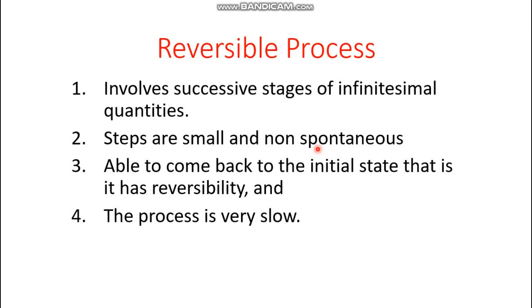and if the steps are small, then it should have the capability to come back or revert back. So the reversible process has the ability to come back to the initial state, that is, it has the reversibility, and from this name it is named the reversible process. So if the path you are choosing has small steps, has the non-spontaneity, and if it has the tendency to come back to the initial state, then that is a reversible process. And another thing, if you are jumping from some height to some lower altitude, then you will take a fraction of a second, but if you use the stair, then it will take some time. So the reversible process is a very slow process, whereas irreversible process must be some fast process.